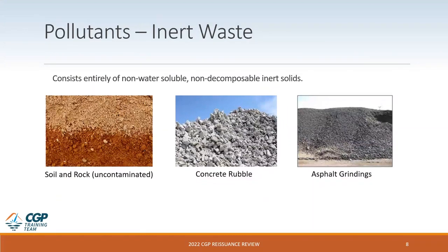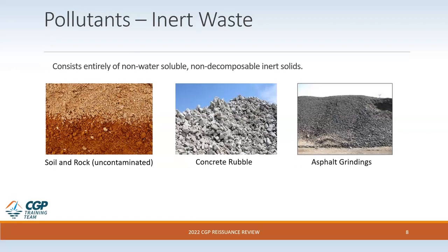Let's take a moment to talk about how the Regional Water Quality Control Board defines hazardous and non-hazardous waste. The first category includes inert waste. Inert waste is waste which is neither chemically nor biologically reactive and usually doesn't decompose. This category consists entirely of non-water soluble and non-decomposable inert solids, like uncontaminated soil, rock, concrete rubble, and asphalt grindings.